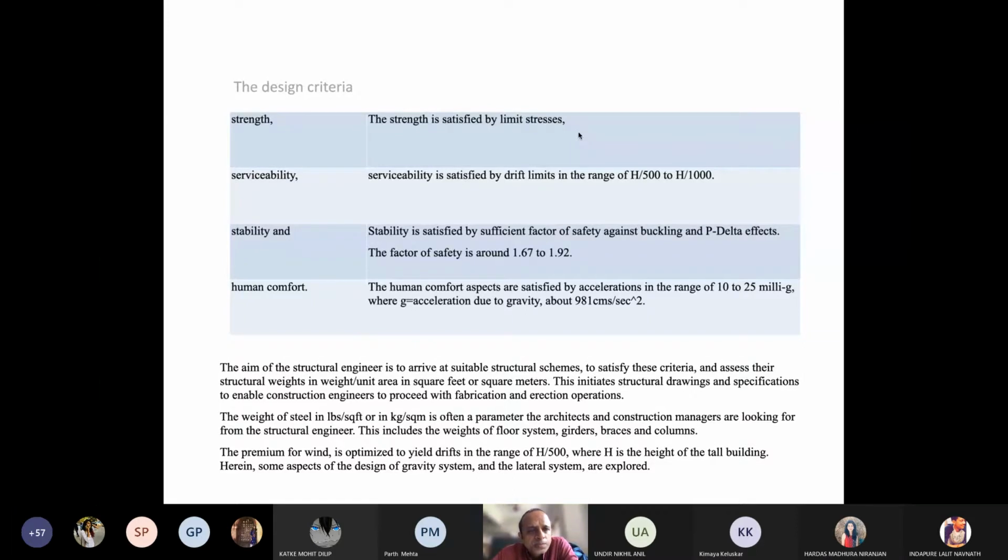designs. Serviceability is something where when we are considering a sway in a building, the top building is moving at the displacement is almost to the within the limit range of h by 500 to h by 1000. There is a possibility that all your AC, all your lifts, shafts, and all, they will also have to tolerate those kind of deflections, right?